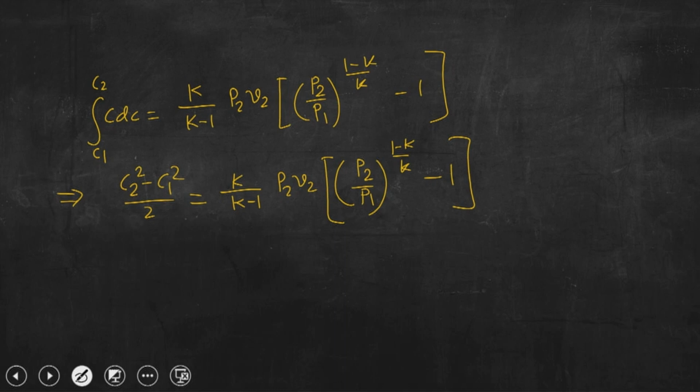Till now we have discussed the critical pressure ratio and mass flow rate. It is the pressure ratio at which the area is minimum and the mass flow rate per unit area is maximum, right, and the corresponding pressure at the exit is the critical pressure.